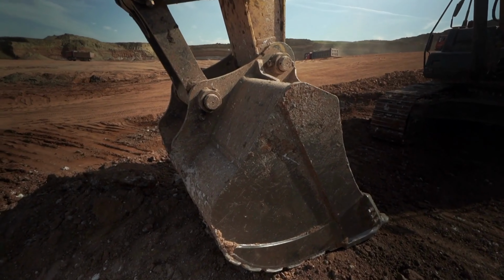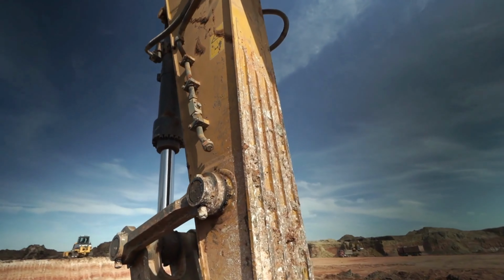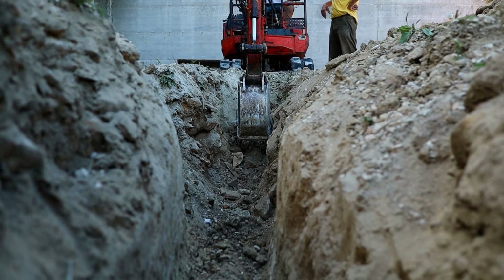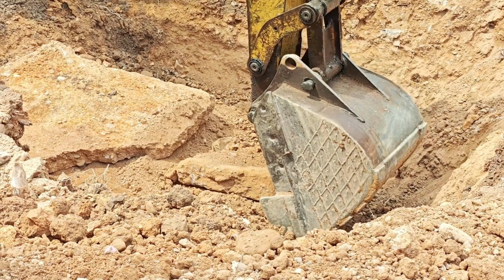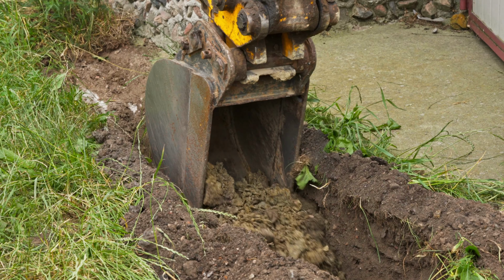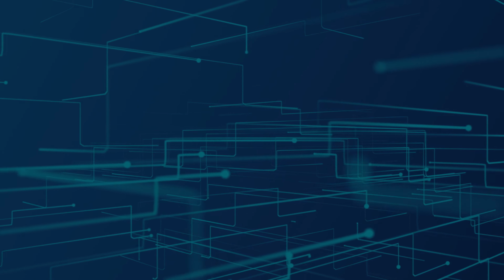Instead, the excavator linkage acts as a mechanical transmission system that amplifies or reduces the applied force depending on the geometry of the mechanism. As the bucket moves through its digging path, the mechanical advantage changes continuously, which means the effective digging force also changes dynamically during the excavation cycle. This is why excavators are designed so that maximum force occurs near the initial bucket penetration stage, where soil resistance is highest.